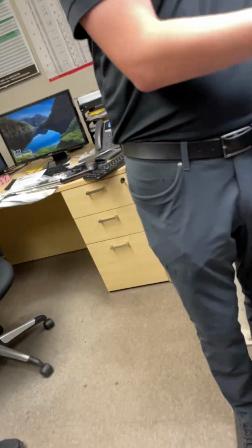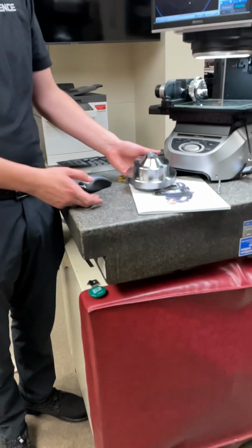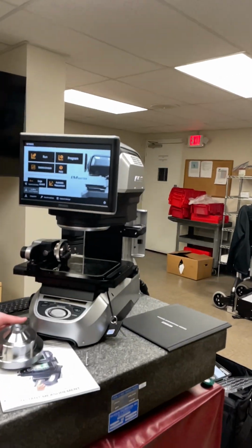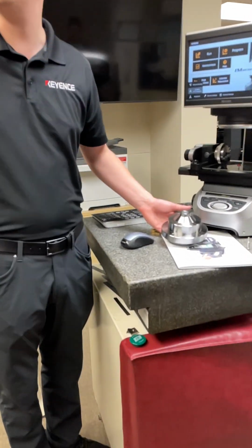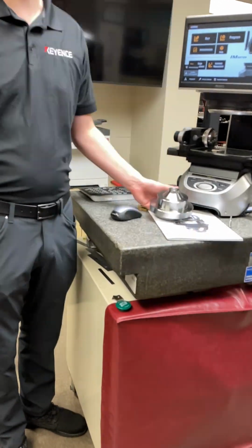What about the other side, the ID? You'd have to put it on there like this. So you'd make a combined program, which is really easy to do. You just make your two separate programs, go down to integration, and then combine multiple programs. Then you save that as its own separate entity, and rename it as combined part number or whatever.